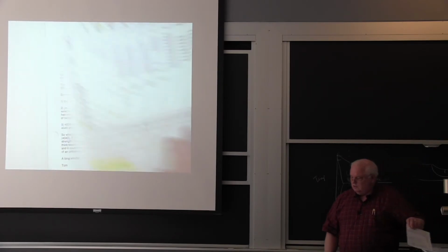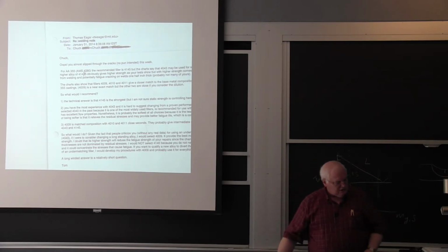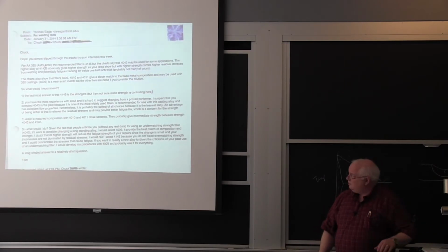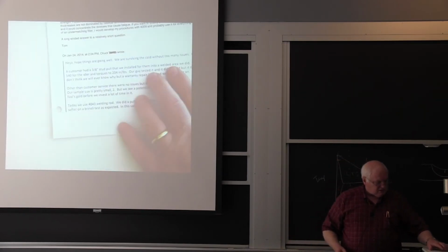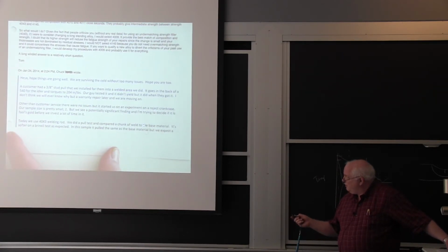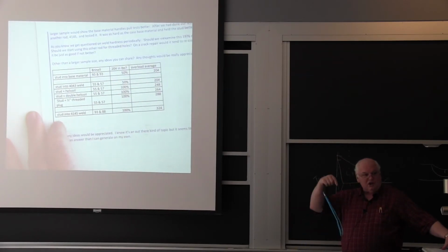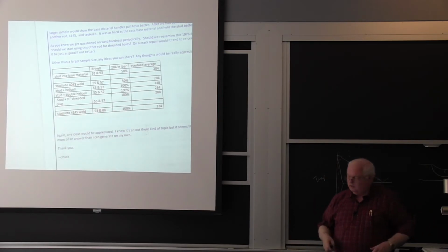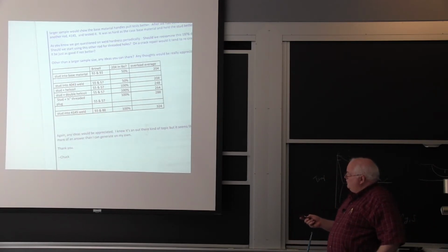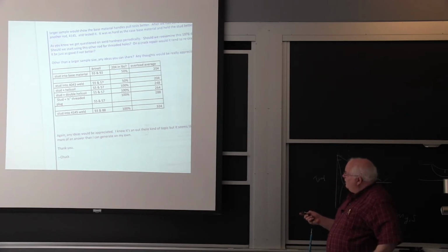Okay? So anyway, this engineer at this company that's repairing engines says, well, we ran a little test. And actually, this is his email to me down here. He basically says, we ran a little test, and if you flip it over, the test shows that they put these steel studs into this casting so that you can bolt the 2 halves of the engine together. If you just put the stud in the base material of the 355 casting and you torque it, you measure the hardness, you'll get a Brinell hardness of 93, and he did it 2 times, as he says.